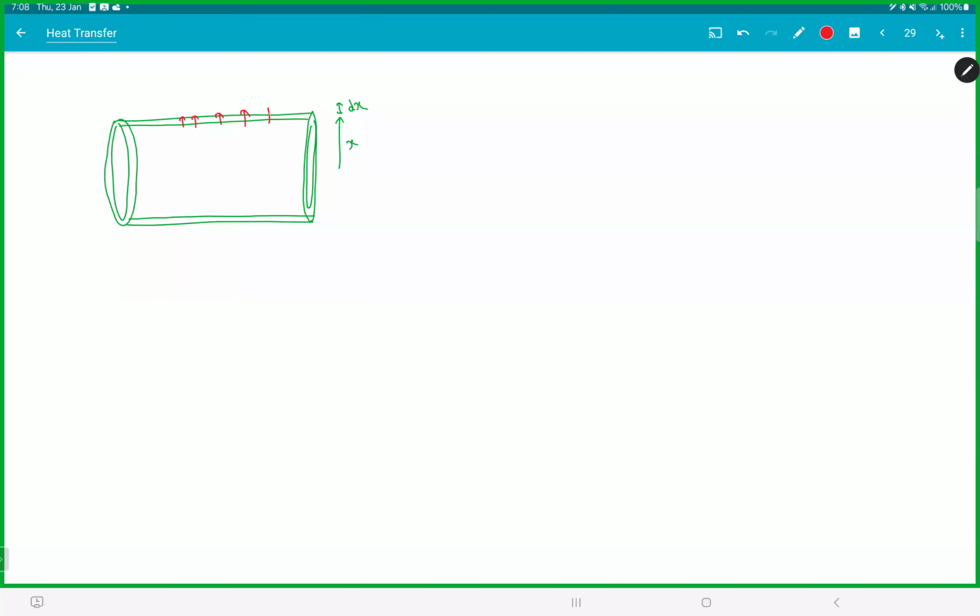The heat is flowing like this. Now, can you tell me what is the length? In the formula L by KA, what is length? Length along the heat flow, which is dx, na? Heat is flowing across a thickness of dx by K. What is the area? 2 pi x L, na? The surface area of the cylinder. A is the area perpendicular to the heat flow.